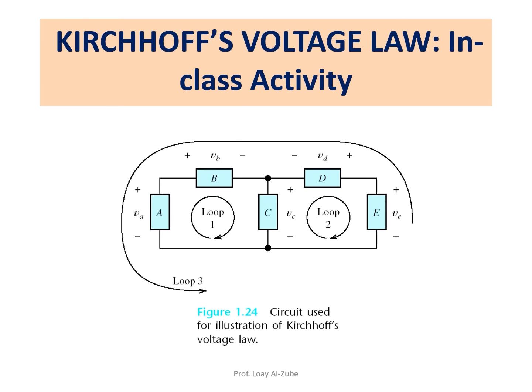So let's say you have this circuit, correct? If I asked you, how many loops do we have? 3. Now, in order to have a circuit functioning well, you need to have the summation of voltages equal to 0 in all 3 loops. You can't miss any one of them. So can you give me the Kirchhoff's equation for loop 1?